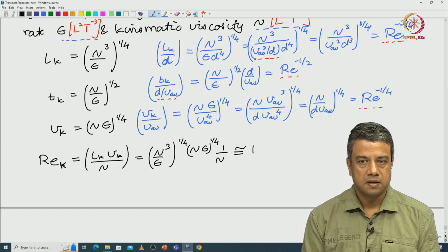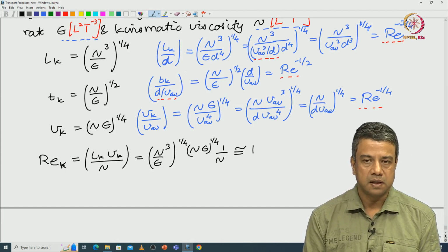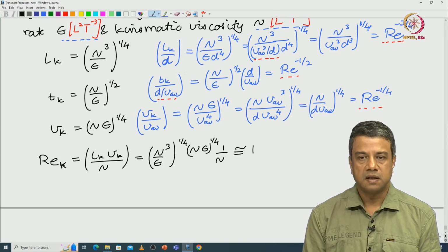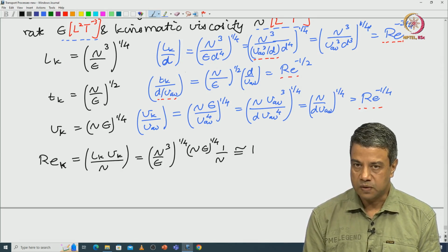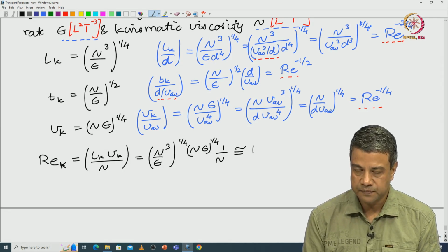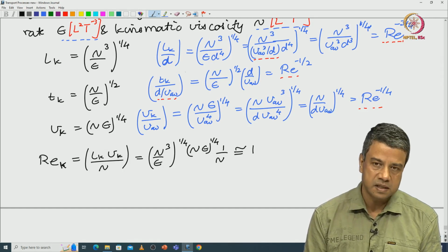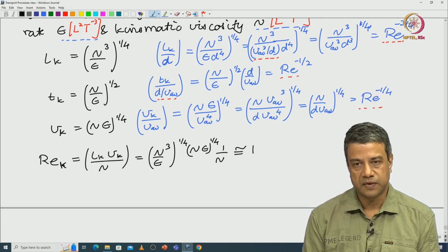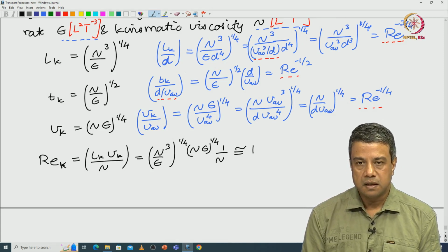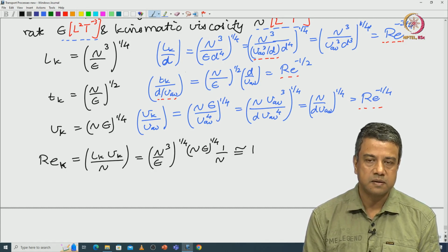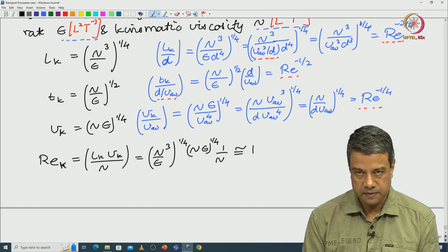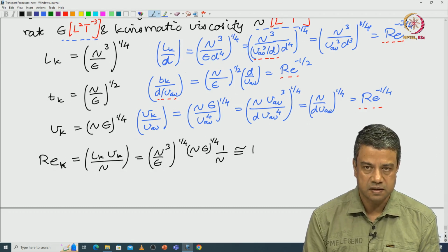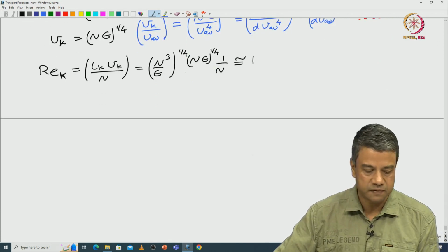Okay. So, the picture of turbulent flow is as follows. The Reynolds number based upon the large scale velocity is much larger than 1, high Reynolds number. The largest eddies, the Reynolds number is large compared to 1, which means that inertial effects are much larger than viscous effects. Since the energy that is put in at the large scale has to be dissipated at the small scale, this implies that for the large scale flow, the energy dissipation rate is much smaller than the rate of input of energy. However, the flow creates smaller and smaller scales in such a way that at the smallest scales, the Reynolds number is order 1, and therefore, the energy dissipated is comparable to the energy that is put in at the large scales, and thereby all of the energy is dissipated due to the creation of these small eddies.